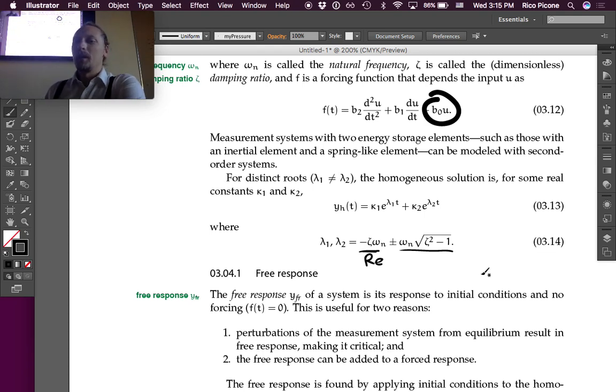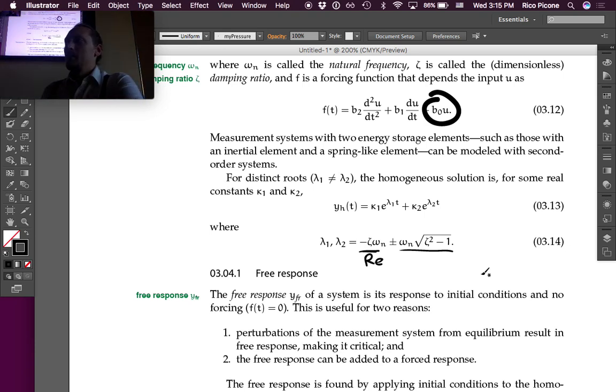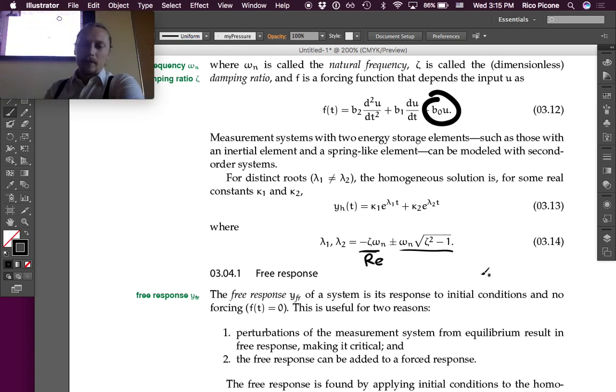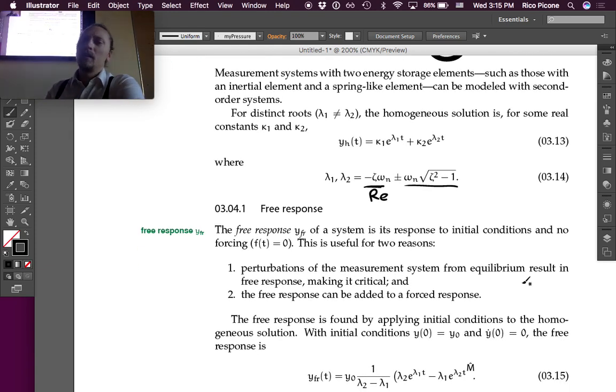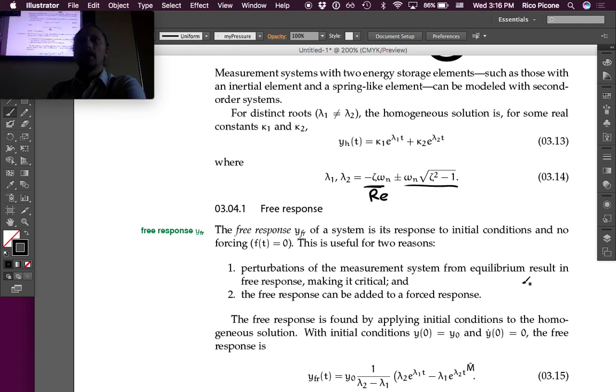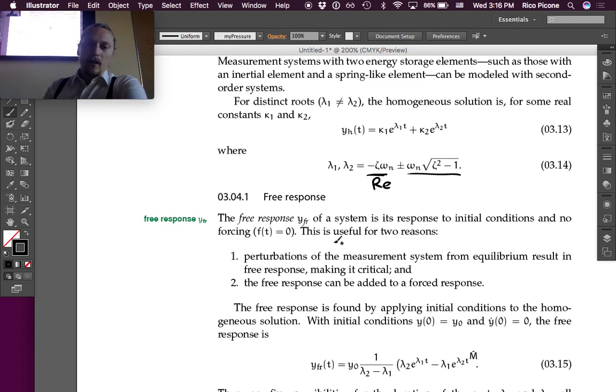For instance, somebody might have seen the Q factor, the quality factor, which is essentially the inverse of the damping ratio within a factor of 2. In mechanical engineering, these are by far the most common way of presenting it. In electrical engineering, sometimes you see Q instead of zeta, but otherwise, very common. So, we're going to focus today on the free response of this system.